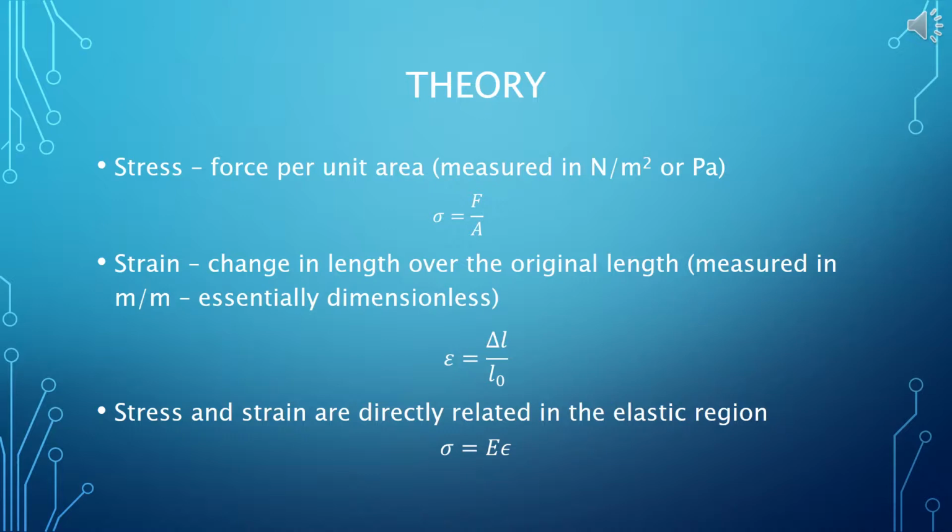Finally, stress and strain are directly related in the elastic region, given by the formula below, sigma equals E times epsilon, where E is Young's modulus or the modulus of elasticity.